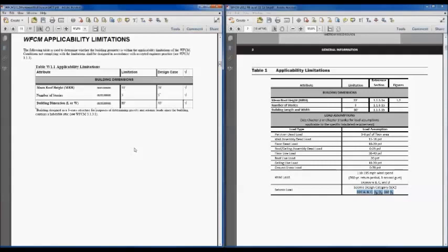So we've covered the loads. We've talked about some of the supplemental worksheets, and about whether we can actually use the Wood Frame Construction Manual. We see at a glance that yes, we're within the loading conditions that would allow us to use it. Now we want to look at whether we can actually use the prescriptive provisions. I'm going to walk through our design case here, and if you have a hard copy, notice there's a typo here. This design case is actually 24.7 feet, just a little shy of 25 feet, so you can make that adjustment to your copy.